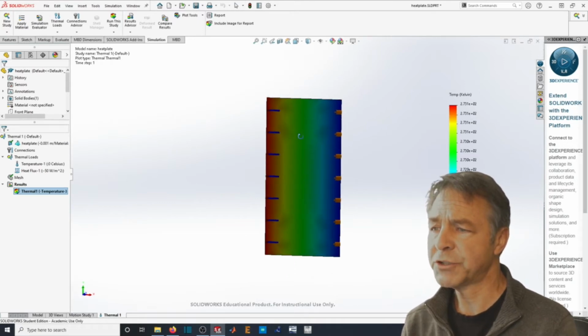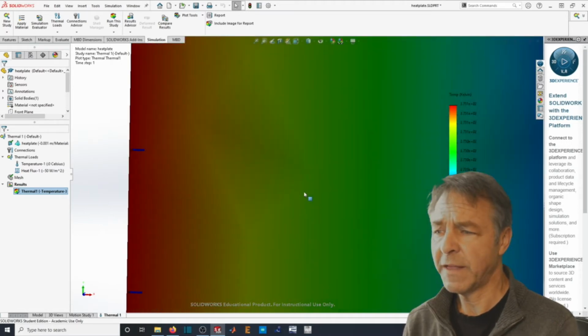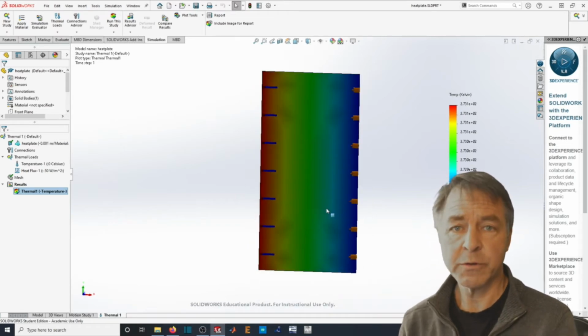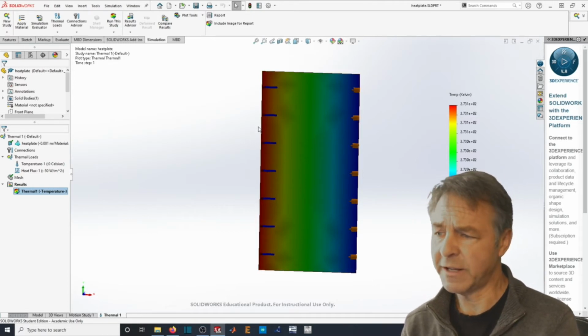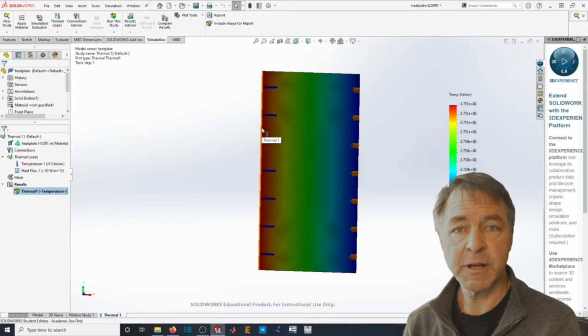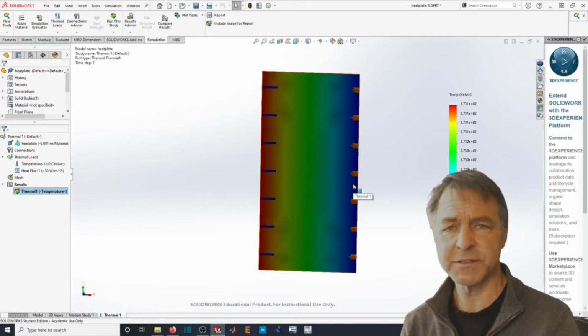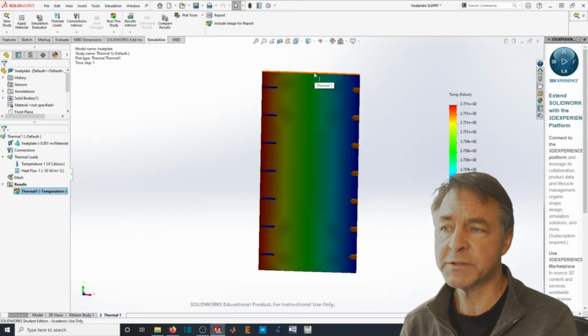Now with this mesh, what's all this? That's an interesting change. And if you don't question the meshing, then you might think that that's really something going on. And yet this is purely a constant temperature here and a constant heat loss here. So we should not see any kind of strange feature like that. This is a purely two-dimensional problem, nothing interesting. What's assumed in this is a thermal boundary layer, basically fully insulated here and fully insulated here.